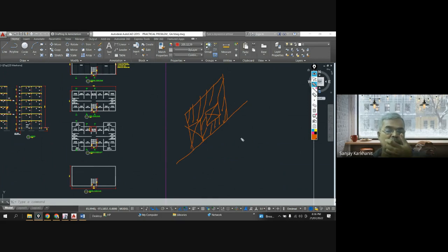Then अगर आपको कंसिडर करना है तो क्या करना पड़ेगा? So find out the total area, and find out the opening, and find out the percentage of opening, and you can apply that factor to this 9.31 multiplied by, let's say, total area of opening is 0.15, means area of BB masonry will be 0.85. So you may say 0.85, and this value you can put in your calculation.